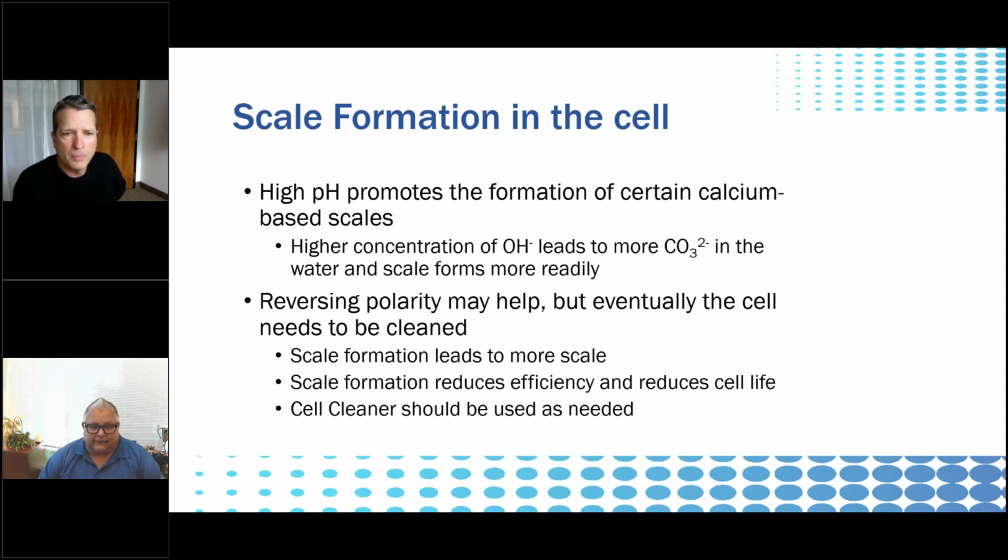And that's simply because as that scale builds up, it's very sticky, it's very gritty, and it will adhere to those metal plates. And the whole point of the metal plates inside of the salt cell is that's what's conducting electricity back and forth through the water. Without the electricity, we don't break apart the salt molecule. If we don't break apart the salt molecule, we don't form chlorine gas, we don't form hypochlorous acid, and we don't sanitize the pool.